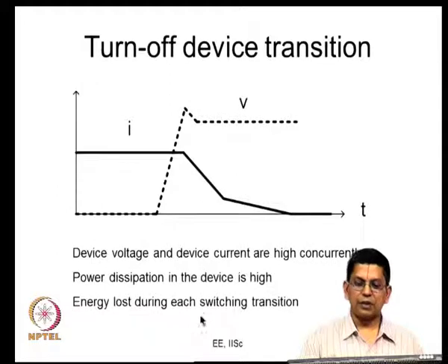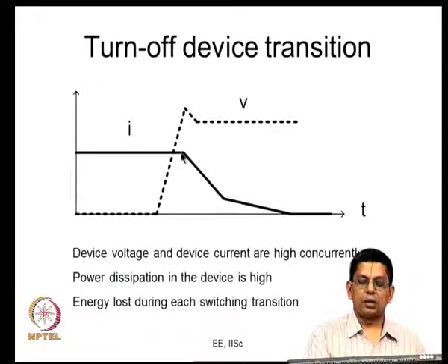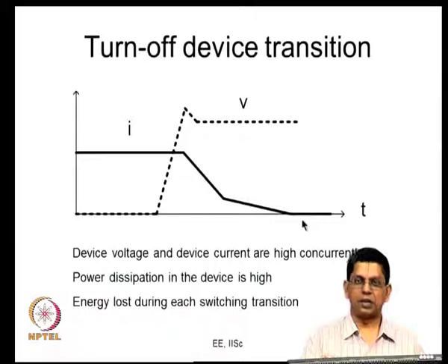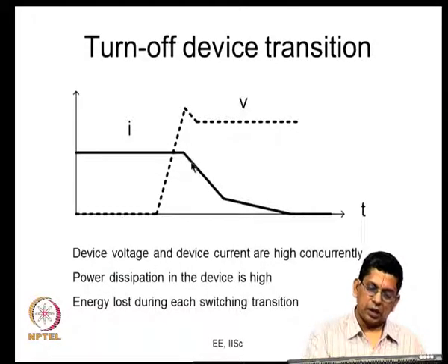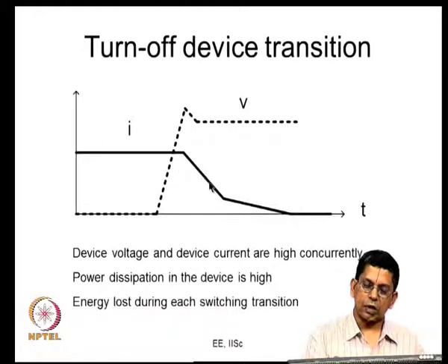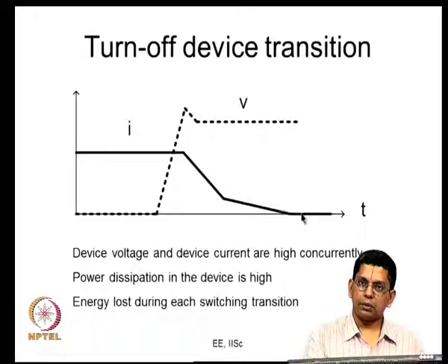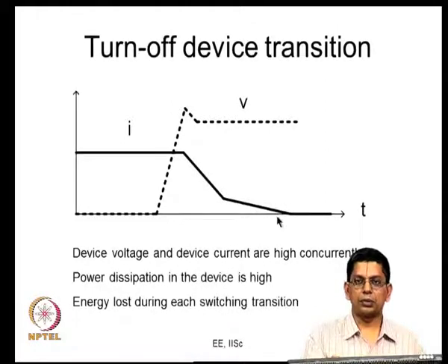Similarly, let us say the device is turning off, it is conducting some current and that current falls when it is turning off. It may fall rapidly, and sometimes it may fall rapidly initially and then slow down. So it is more gentle than this, and sometimes you can represent that as a double slope. That is, instead of falling sharply all the way down, the current initially falls sharply and then slowly tapers down. This part is represented asymptotically like two straight lines for convenience, and this is sometimes called tail current, because it is like a tail.